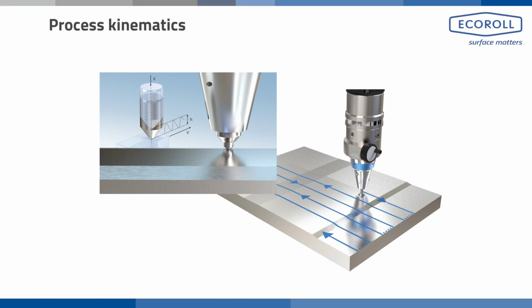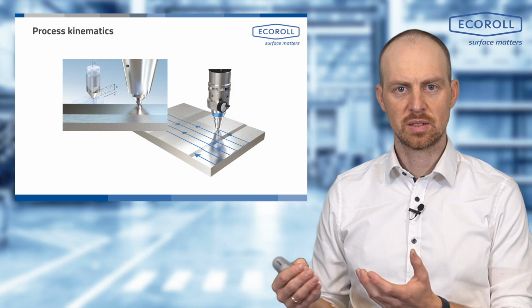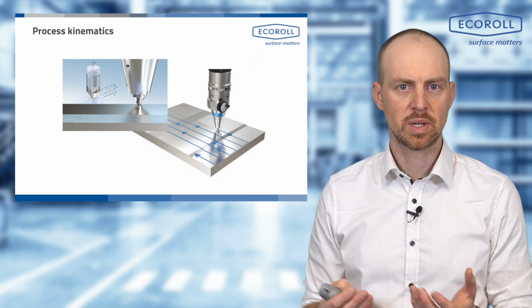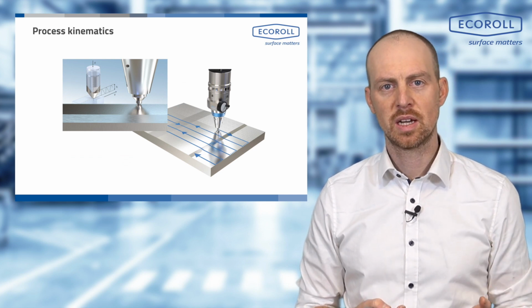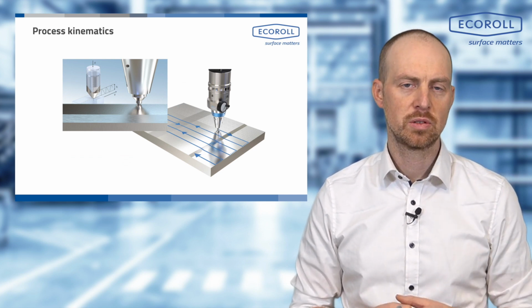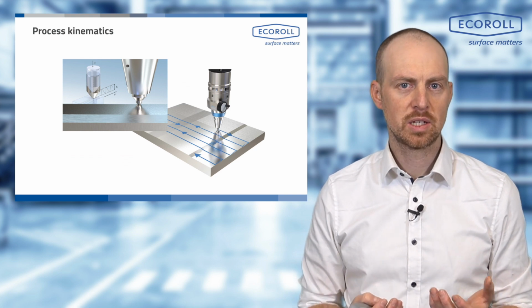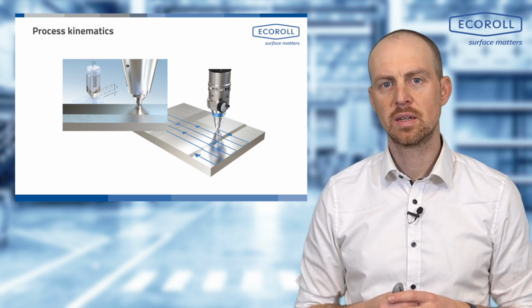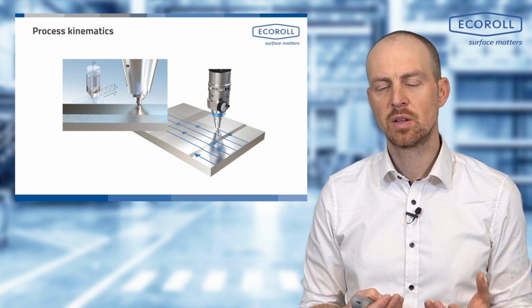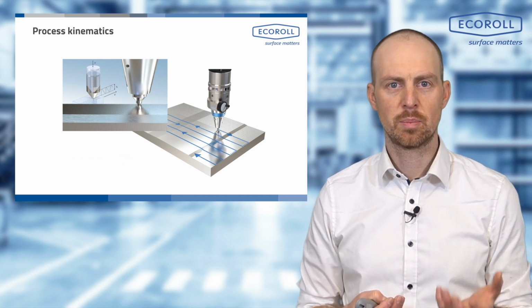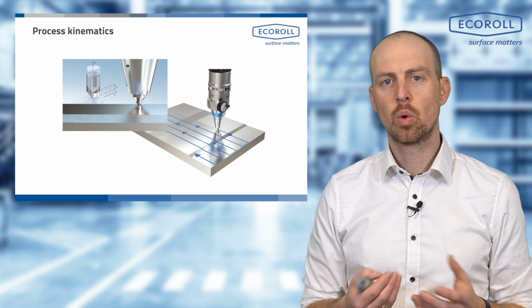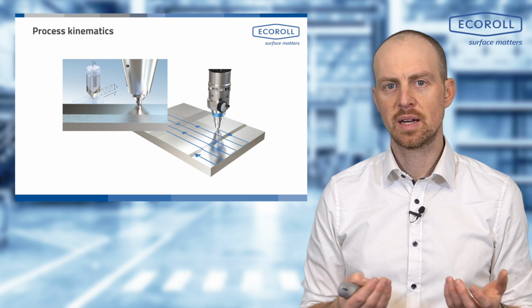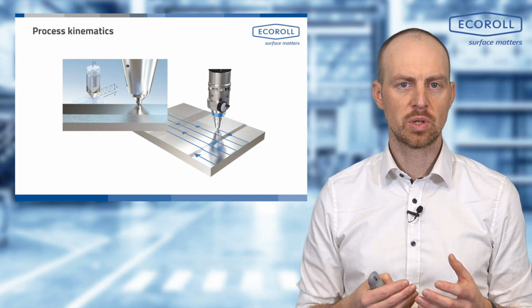Basically, there are different types of tools for hammering. There are systems that work electromagnetically. For those, I need an electromagnetic generator, which allows me to very precisely control the acceleration of the hammer onto the surface. The whole thing can work pneumatically, the whole thing can work piezoelectrically. This means that I have a piezo actuator that briefly expands and thereby drives this hammerhead onto the surface. Or, as in our specific case, I can have an electro-pneumatic solution that we have.